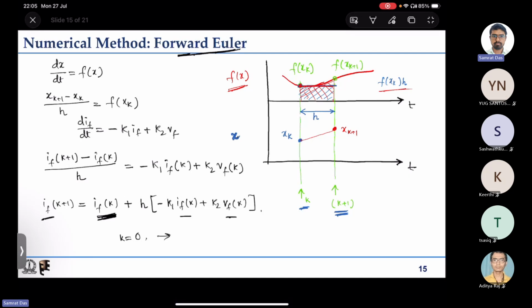So because we gave the field current an initial condition, the integration of that, what I am talking about is this is vf, this was if into rf. This was integrated, okay, this was 1 by lf, and it was integrated, and the output was if, and it was multiplied with this rf, and the IR drop was subtracted. So for this integration block, you had to define some initial condition.